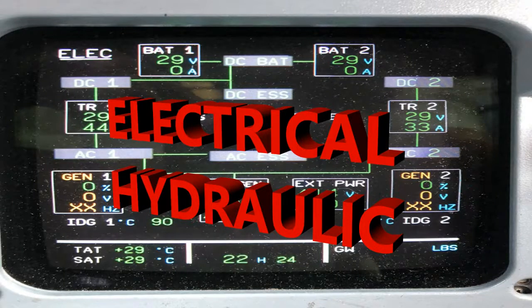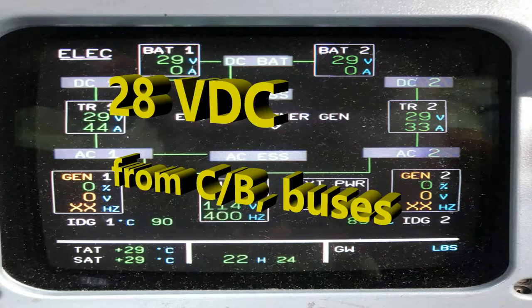On electrical, the source is going to be the circuit breakers coming from the different buses that are rated 28 volt DC. The primary computers, also with the remote gyro and accelerometer units, are connected to those 28 volt DC buses.